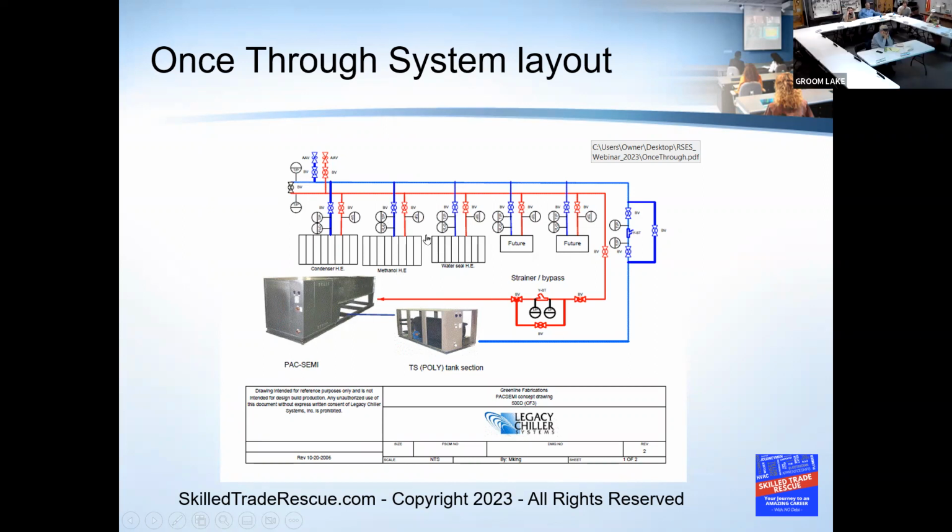Changes it. That's right. So the other one they'll have a problem with is when nobody knows this is there. They don't make any change, and they shut down 1, 2. Maybe they leave this one open. They cut back. So then before they know it, they don't know this is happening, but all of a sudden this thing goes out on low suction, right? Because what happens is, just like any refrigeration system, if you cut off load immediately by lack of medium moving across it, your TXV valve is gonna say, "Whoa, my superheat just took a dump," right?